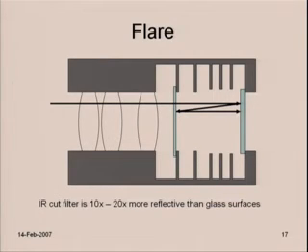So the problem with these IR cut filters is that there's a number of different ways of building them, but one good way is to use stacks of material like those broadband anti-reflective coatings that I showed earlier. But instead of using 4 materials stacked, these typically use like 25 to 30. And sometimes they might have both sides of this, what's called a plano-plano element, very thin piece of glass usually.